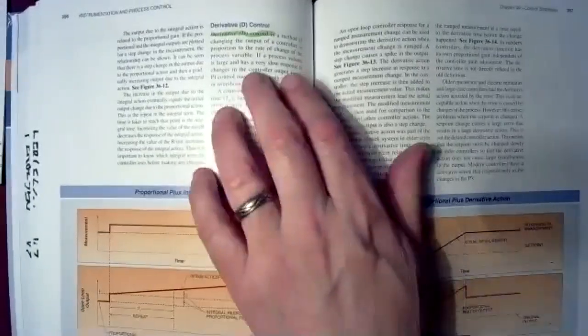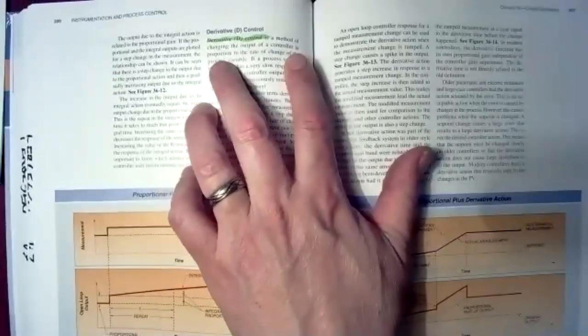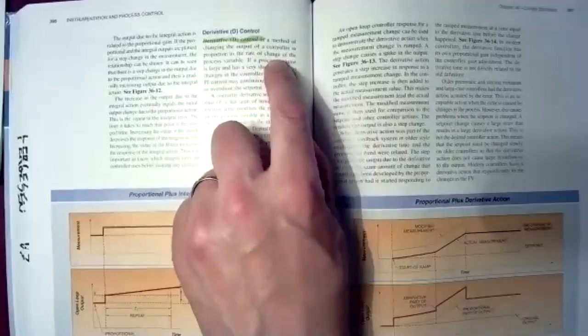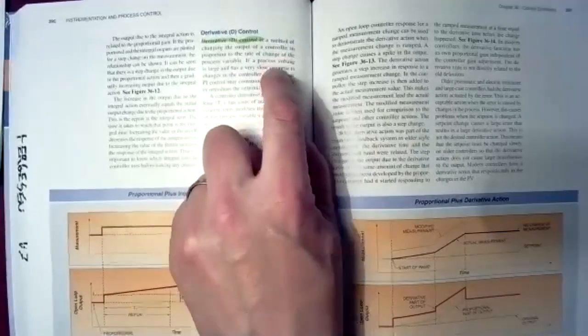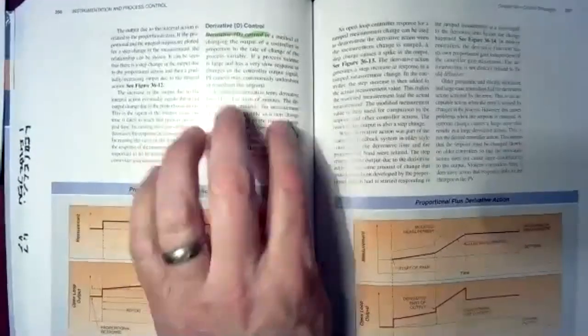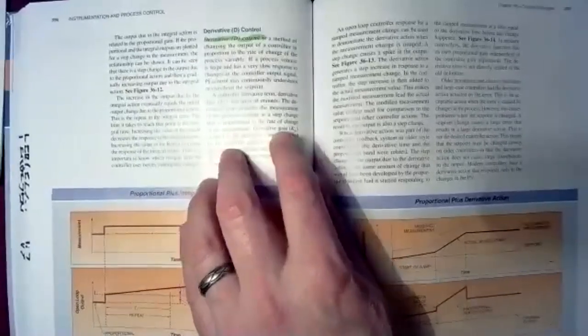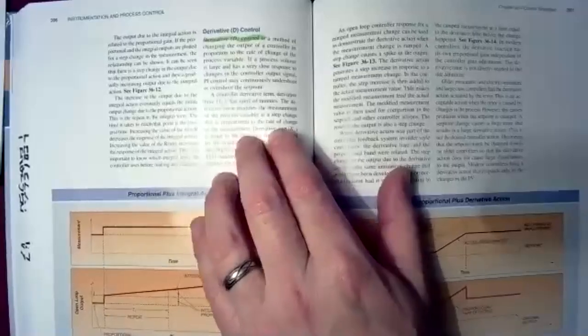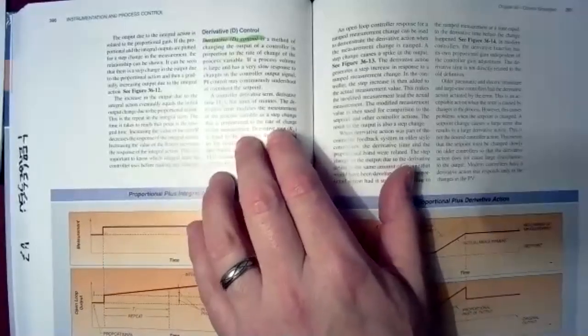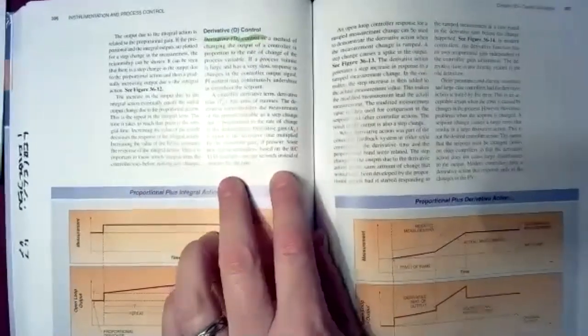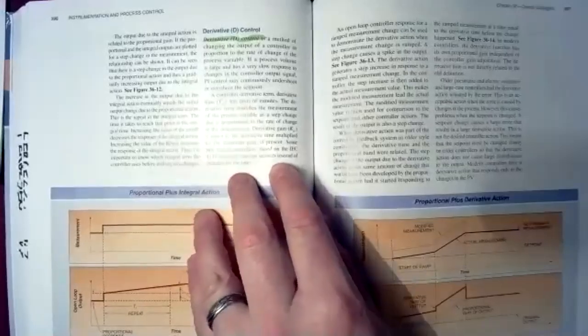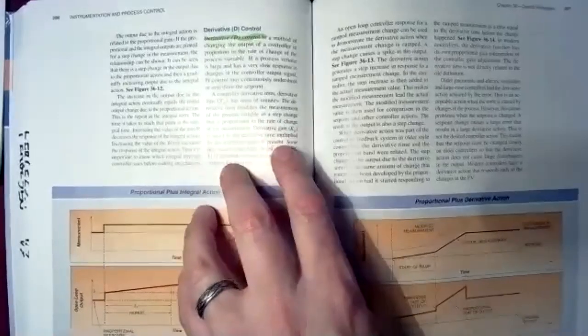You can read about how the derivative control works. It's a method of changing the output of a controller in proportion to the rate of change. So that way, the faster your temperature changes, the greater the derivative effect is on the control mechanism. For instance, if I drop a huge chunk of cold chocolate into my vat in my chocolate factory example, that rapid change in temperature to the rest of the chocolate will trigger more of a calculation inside the computer to say, whoa, I better rapidly open up that valve and get a whole lot of heat into that tank to make sure that we can get back up the temperature quickly.